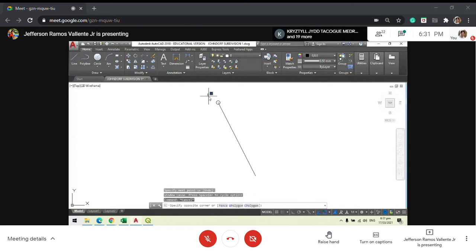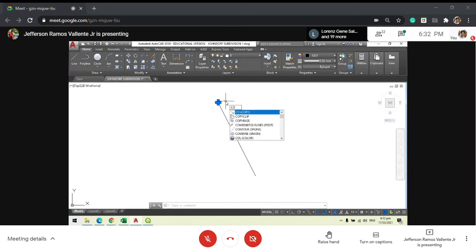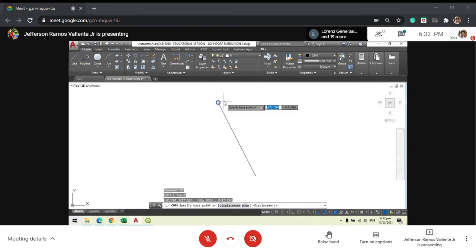I can copy this one, the circle. First, sorry, select this figure or the circle, left click. It should be highlighted with the blue dots. And then input the command CO. CO is for copy, okay? You can also use Control C, but that's mostly for text files.